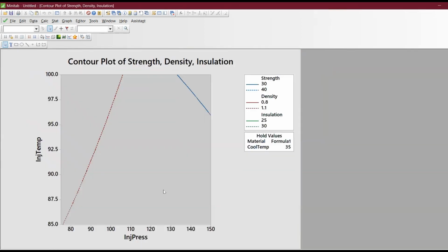You can see that injection value, this 3, 1, right? So at the place of injection pressure, injection temperature, you have those values as well, right? So strength, this is strength, right? These three things, the contour plot is very helpful where we can study three things together. That means if the injection is low and temperature is low, the strength will be high, right? You can easily see that correlation, right? And let's go to the another one.